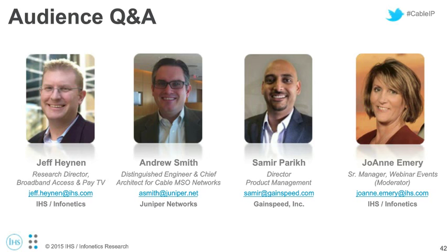Yeah, that's a great question. When we talk about full spectrum DOCSIS, we're talking about the platform that can be used today in a full spectrum DOCSIS environment. So if you wanted to, you could take a 1 gigahertz plant and do 158 6 megahertz carriers as DOCSIS. But we understand that operators aren't going to be able to move to that day one. So it's about providing a platform that they can then leverage the power of software to morph over time to get more DOCSIS as they need it.